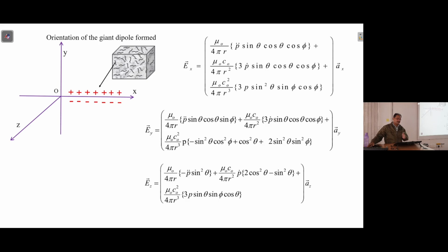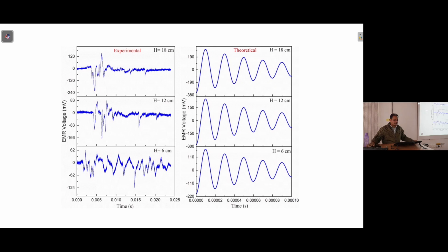And then the same thing we further extended for the mortar sample. There the geometry was entirely different, right? It was cubical, and the antenna types we were trying to use were rectangular sheets at the two sides. So again we had to convert everything to rectangular components, with the geometric parameters associated with this particular experiment. And here also we finally could get matching results.